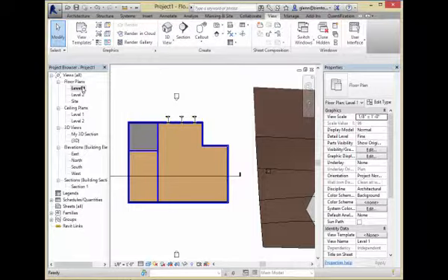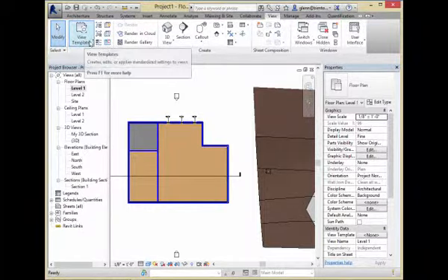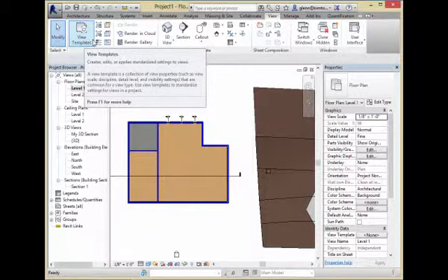But if you use this template, yes. For example, if you want to include some furniture in one view and do not want to include the furniture in another view, but you use the same template, then how about the furniture visibility? Every template, you get to control what sort of things are included in the template as an override and what aren't. So if the template included furniture turned on, anything you apply that to will be turned on. So you'd have to have 2 different ones to do that. So it's relatively all or nothing.